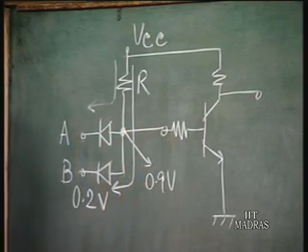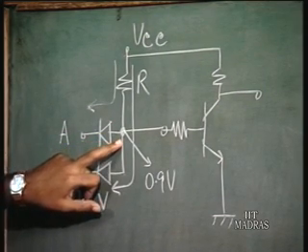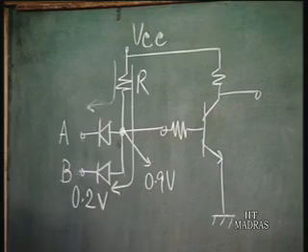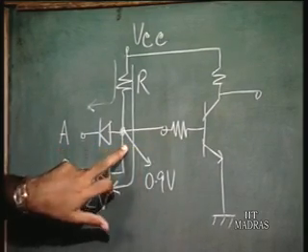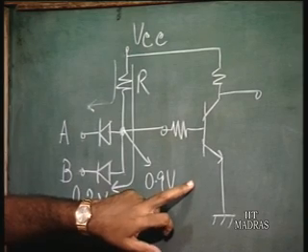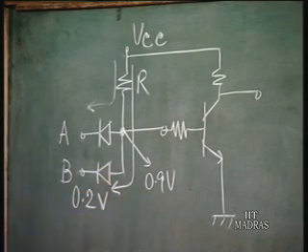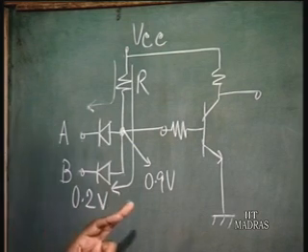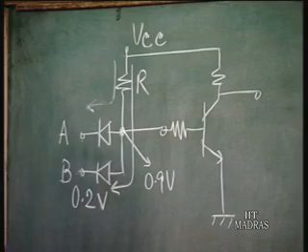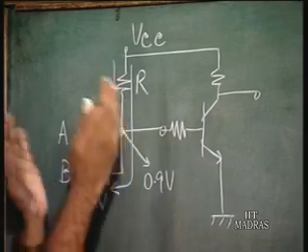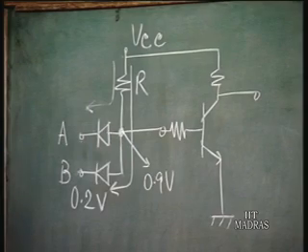So this voltage is 0.9 volts. Now if you have 0.9 volts here, we have seen the BJT inverter characteristics. If this is 0.9 volts here, what happens to this transistor? This transistor is going to be in saturation. But what we actually want is that this transistor should be cut off. When any input is low, this transistor is cut off. So although it looks nice, followed by an inverter, NAND, it is actually not going to work.